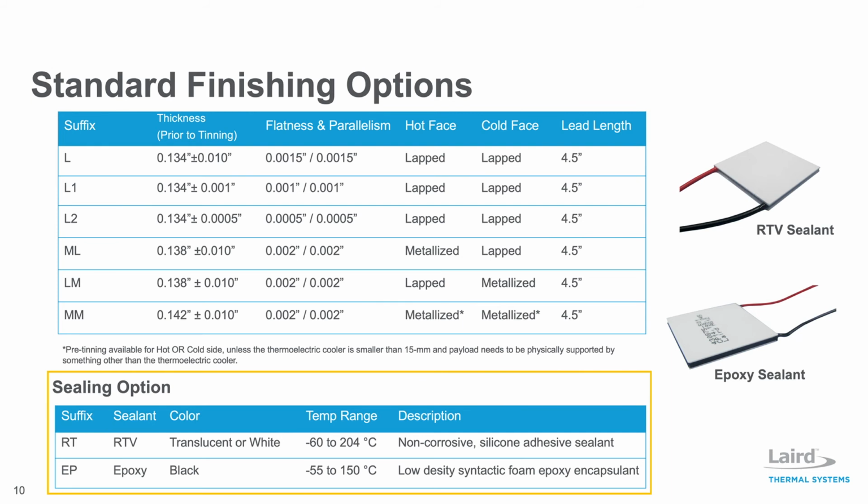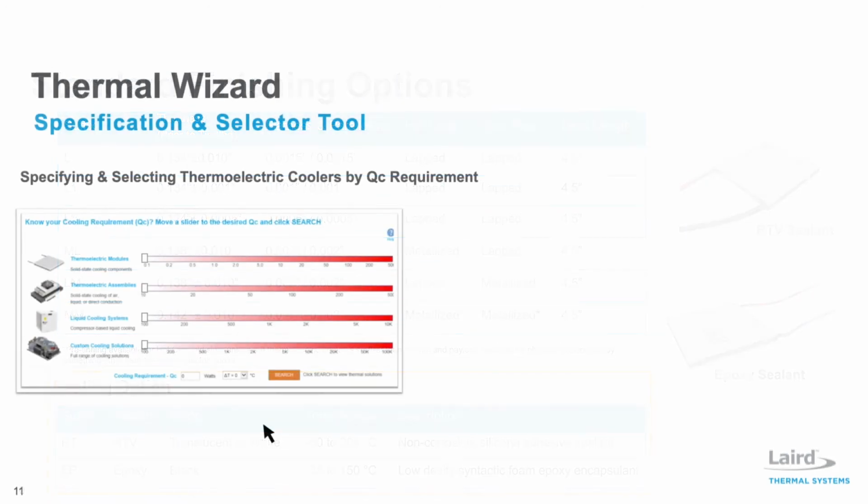However, applying epoxy onto thermoelectric coolers can be cumbersome as multiple fillers are required to be mixed and working life tends to be short, which makes it more difficult to automate for higher volume production runs.